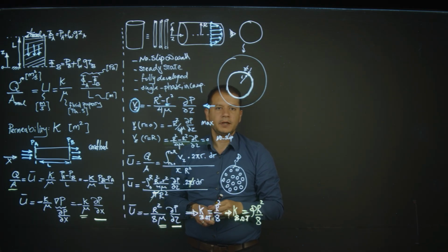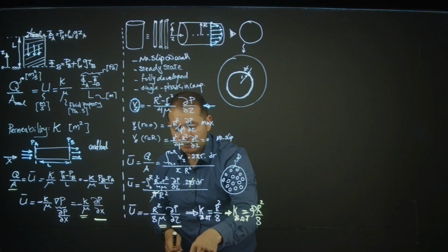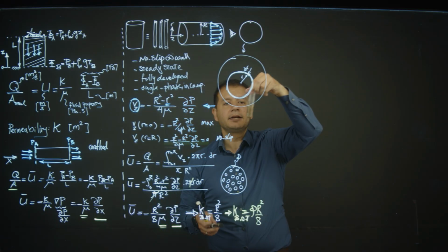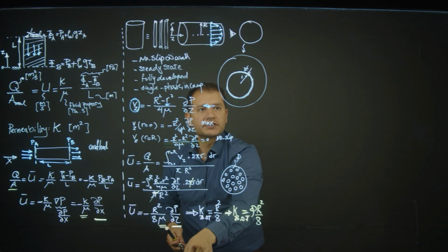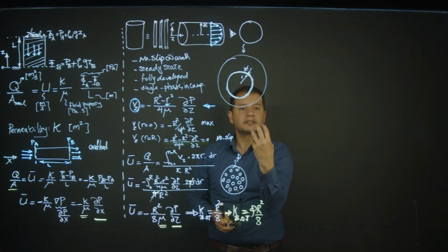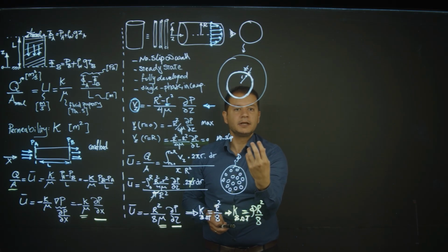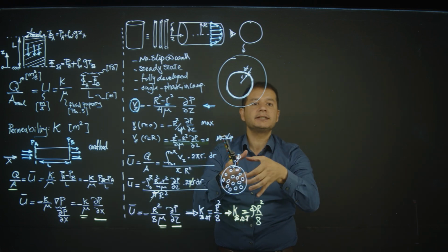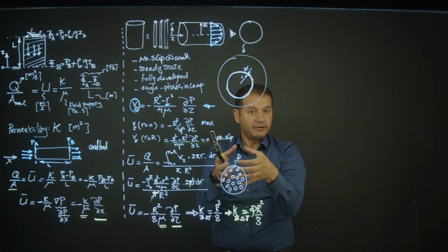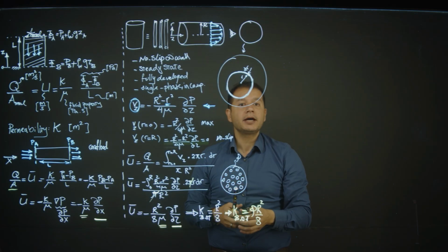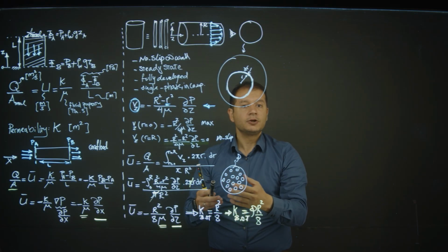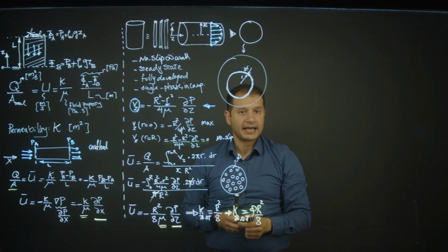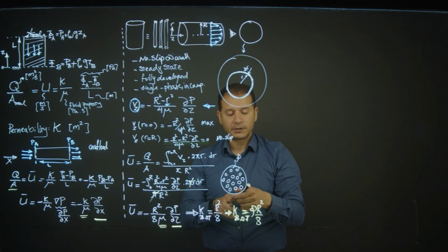Fantastic. Now I would like to find permeability of a sand pack like this. But these are sand packs of spherical grains. Flow through them is not like flow through a cross-section that is circular. It's very complex. So how can I extend it to non-circular diameters or geometries?